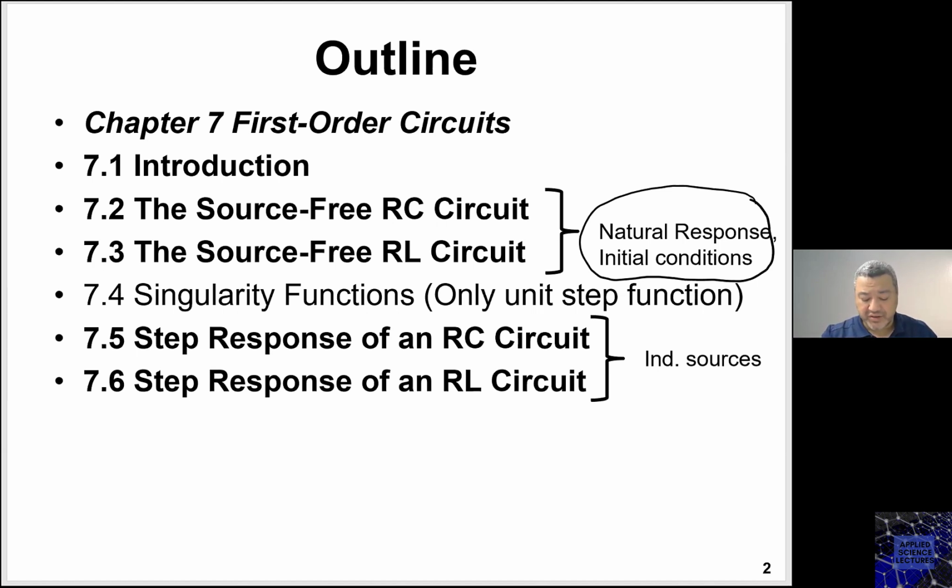And this resistor is the Thevenin resistor. So when you later calculate the resistance, you need to find the resistance that this capacitor or this inductor is seeing, which is all the equivalent resistance connected in parallel with this capacitor or this inductor.